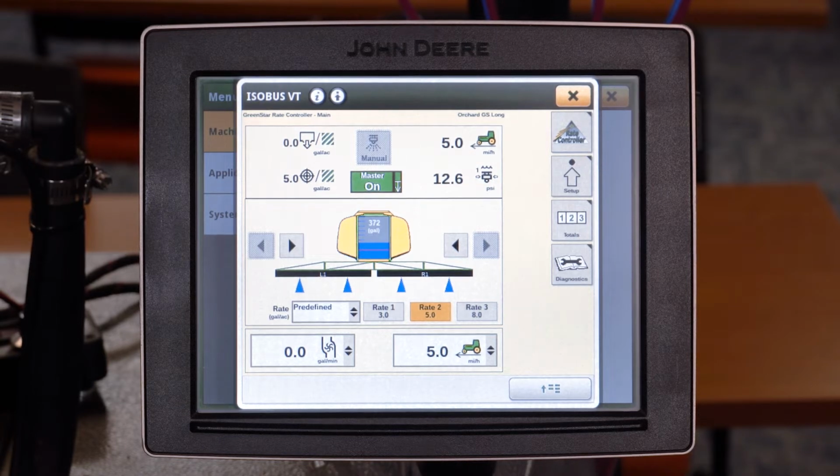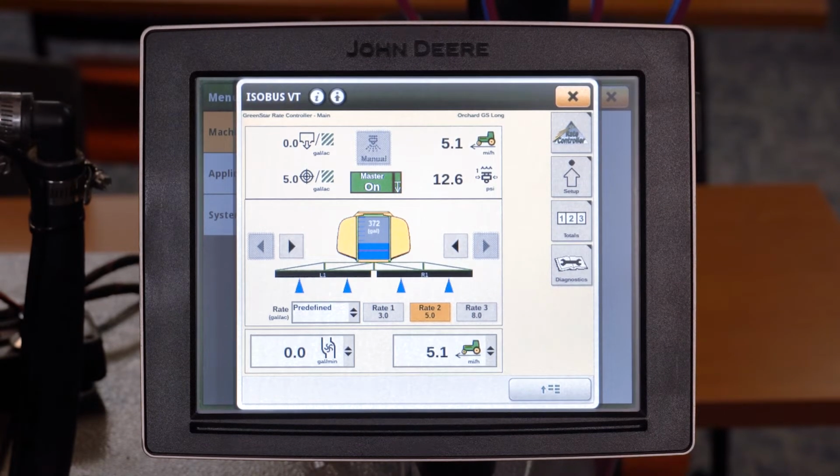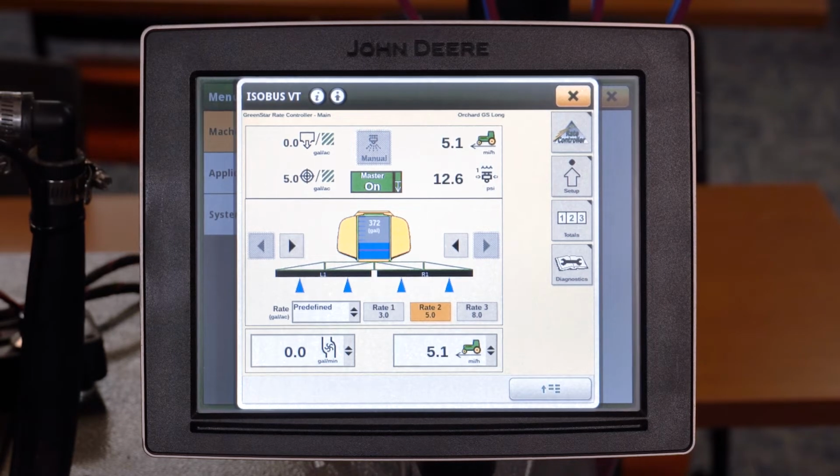Here are some things to check. On your run screen, look at the master switch. Is it showing that the master switch is on? Does the screen report that it's on? Look at the height switch or implement switch. There may be an arrow on the screen. Is that showing that the implement is down in a run position, or is the arrow showing the implement is up? You may need to adjust the implement switch or make sure it's working.